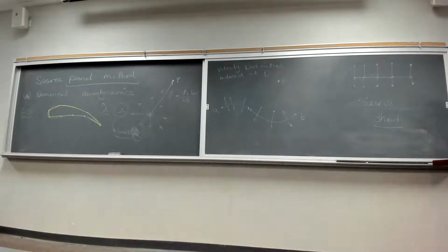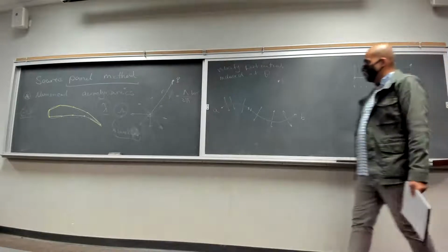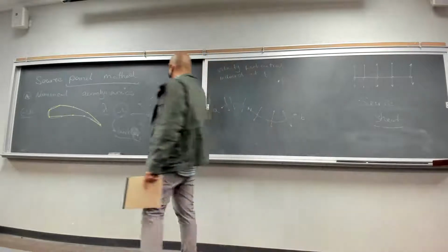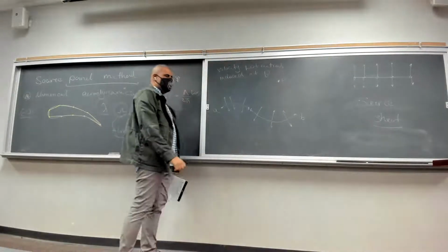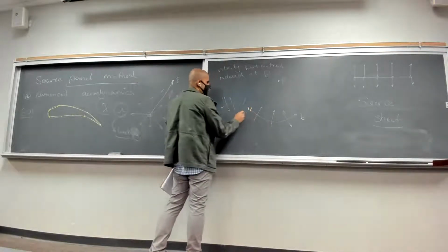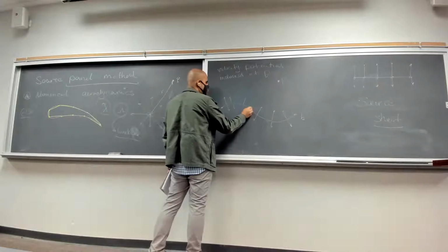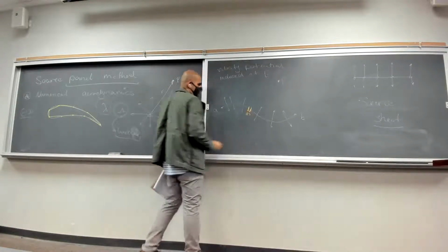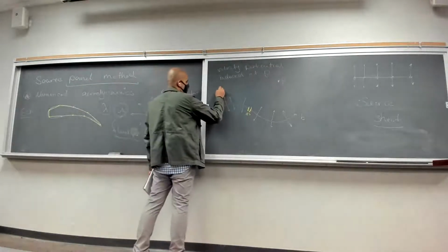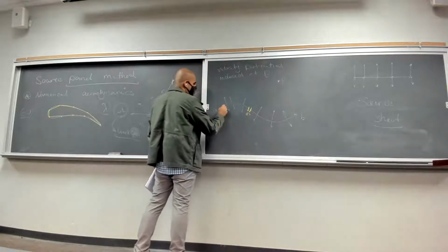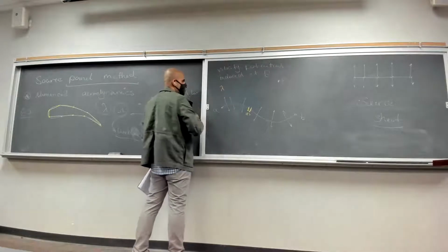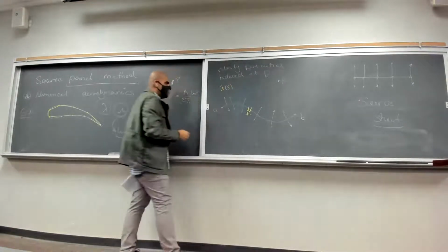Okay. So we want to find the velocity potential phi induced at point P by this source sheet. We take a very small element of this line with the length ds, and we are going to assume that the strength of each source on this line is a small lambda, which is a function of s.